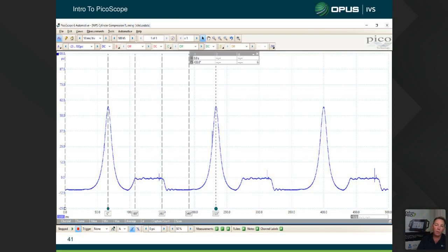So what happens after our power stroke? Our exhaust valve opens. And that's why this value here is back at 0, because our exhaust valve's open. So we're no longer in vacuum in that cylinder. Exhaust valve is open all the way across to here. And somewhere over here at this bit of noise, our intake valve opens, we can see. So the exhaust valve closes about here. Intake valve opens. The piston's now at 180, what's that?